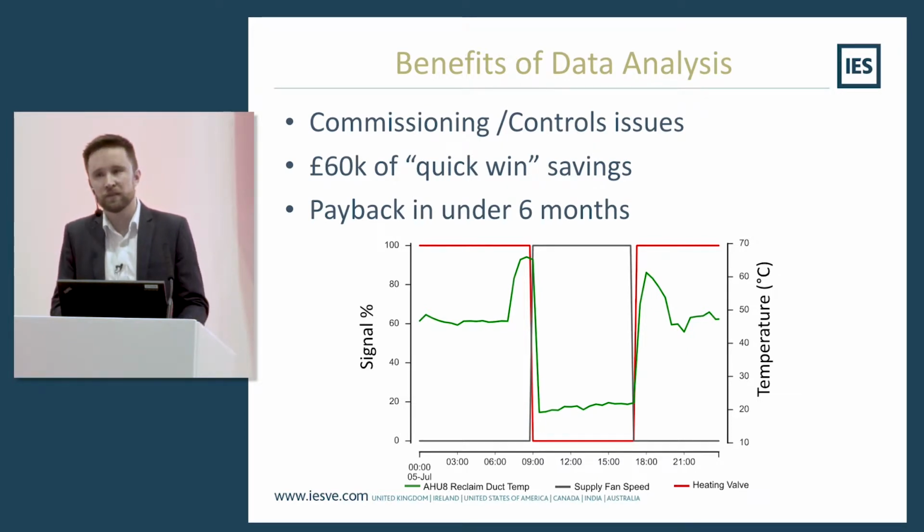So when time to do commissioning is squeezed or commissioning budgets are squeezed, often systems in new buildings aren't performing as they were intended by the designer. By looking at this data with modern analytical tools, you can quickly find savings that can be made just by small tweaks, changing set points, run hours, and also you might find bigger opportunities for savings through capital investment.